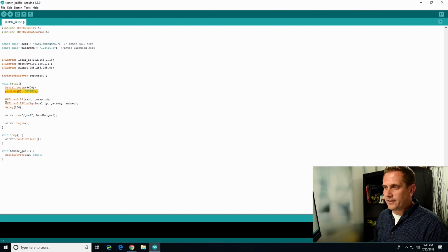And then we're going to say, okay, we want to make sure this is an access point, give it the Wi-Fi name and password from earlier. We'll program in a little delay just because with microcontroller land, sometimes it takes a minute to process. They're not crazy high powered. And so you're going to want to make sure that you give it a little bit of time occasionally. You can mess with that if you need to, depending on which board you're using.